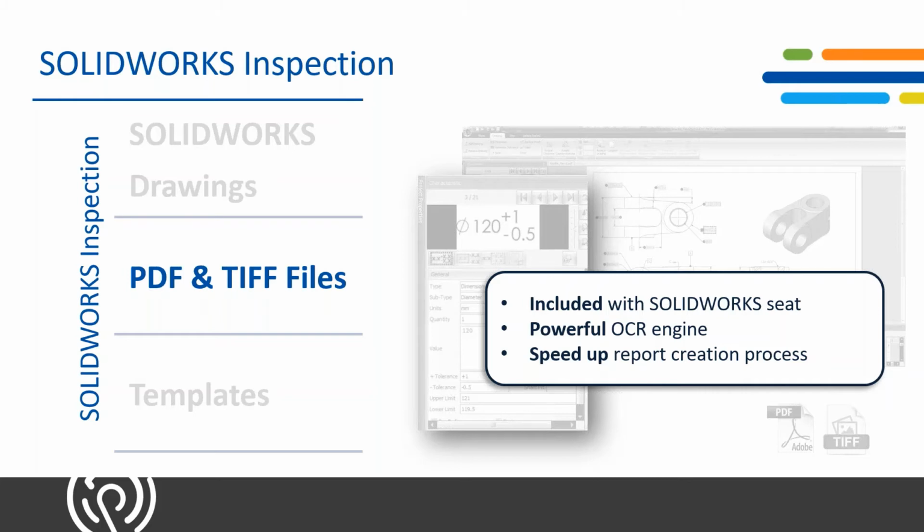Additionally, if you have another revision that comes in and you have to make changes to the balloons, what you can do is overlay the new revision with what you currently have, and then you can just point out the differences and only change the balloons that have changed. You do not have to redo the entire thing when only a few things have changed.